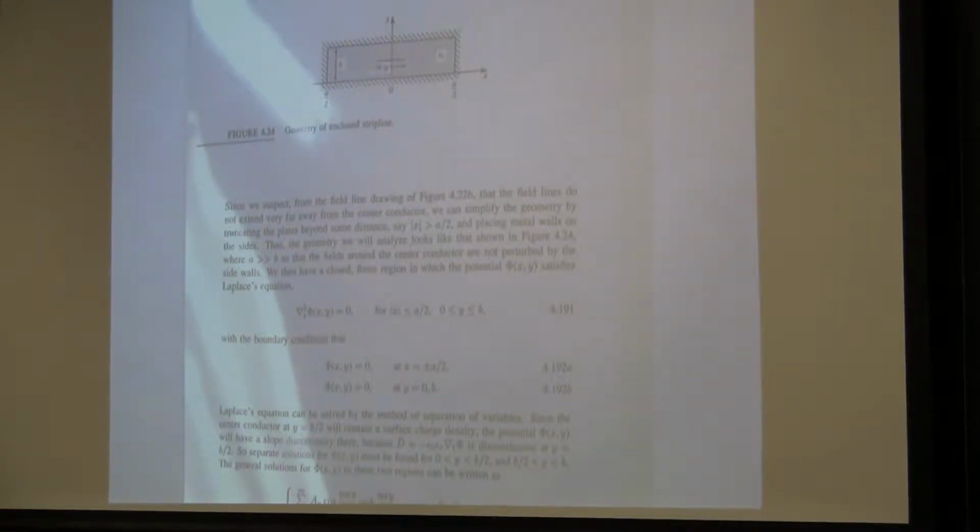Obviously, the impedances are mismatched. So what do we do? We put in between another section, call it MS, the matching section. And we're going to fill it with dielectric. Let's call this epsilon R matching section. And obviously there is the length of the matching section.